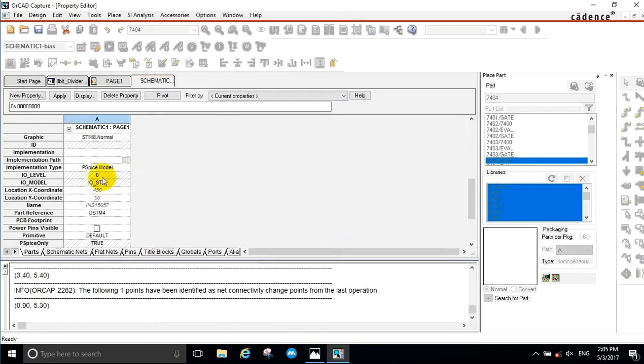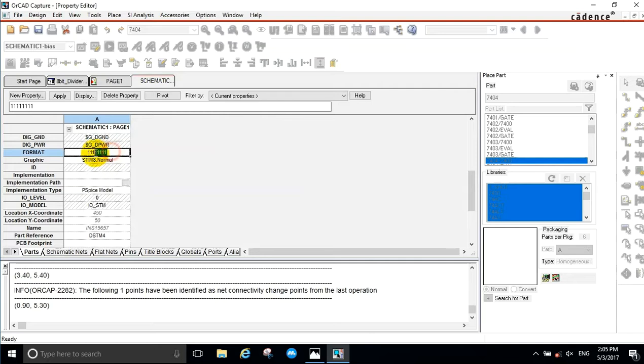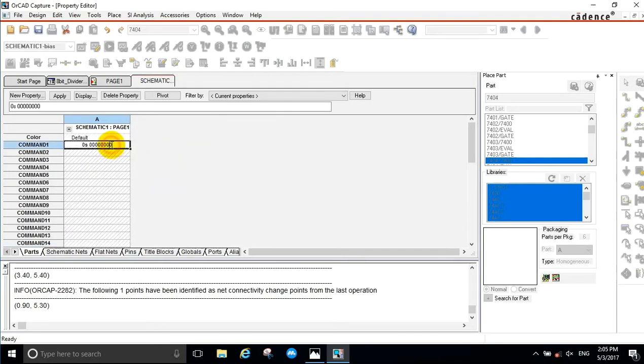We're going to do the same for B, change the format to 4-4 to represent hexadecimal, and change this value to 0. After 50 nanoseconds, we're going to divide by 0F.